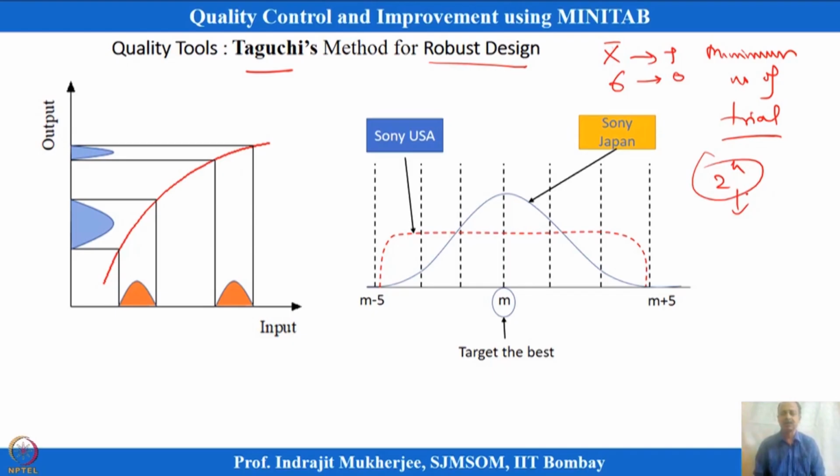So, in that case I do not have to do so many trials, like the full permutation, all combinations of the factors. We do not need that. He emphasized that using signal to noise ratio indices, an index which takes care of both mean and variance, we can get a setting which is very robust, which will bring the mean to target value and also reduce the variability. This is a typical scenario that came when this idea was implemented.